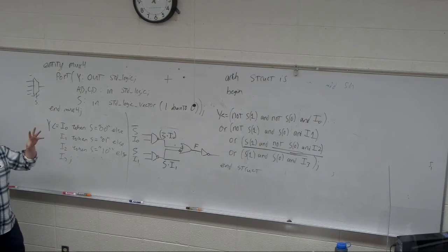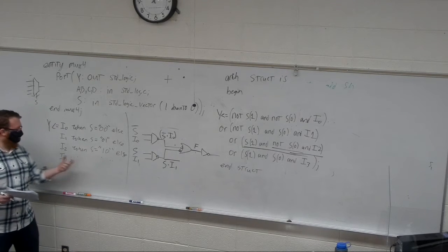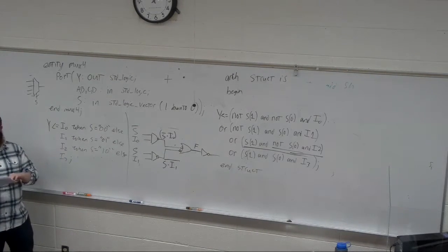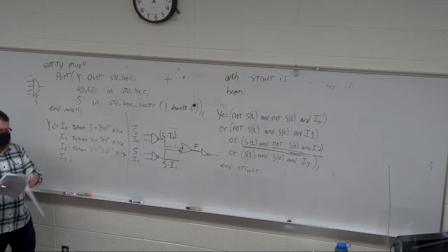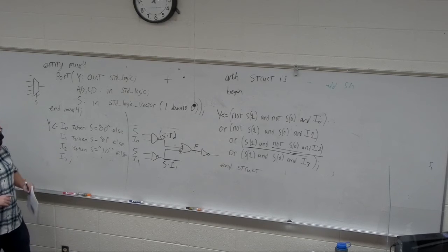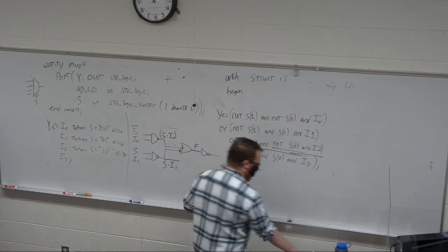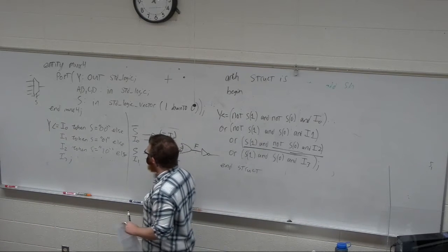Sorry, VHDL calls this one a conditional. Case is a more specific term in VHDL. But basically, on the condition of S, assign Y accordingly. You'll find that very useful throughout your career as a future digital designer. And I'll cover proper case statements later, because I like those more. Any questions here?